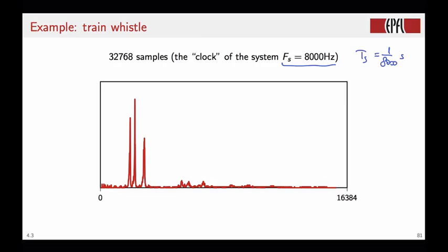So if you take the DFT of this file and plot its magnitude, you see that there are 3 peaks that probably correspond to the 3 notes being played. Now, in order to label the axis, remember what we said. The highest frequency for a digital system corresponds to half the inherent sampling rate. And on the DFT vector, this point will correspond to the midpoint in the vector, namely the point for k is equal to N over 2.